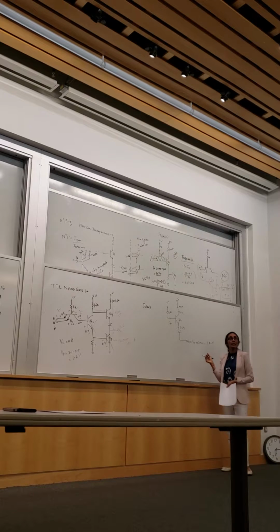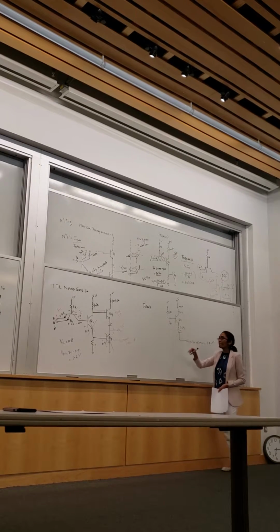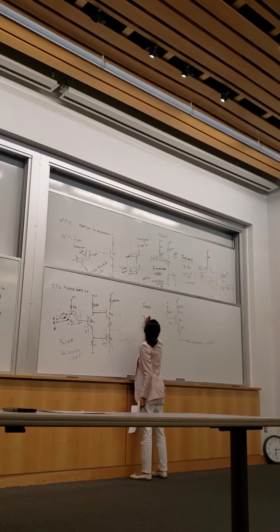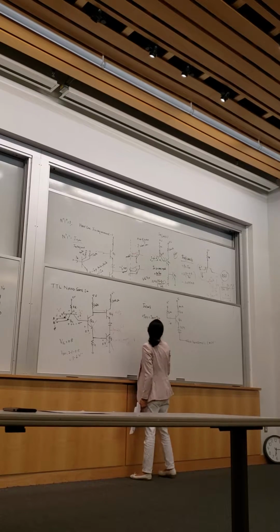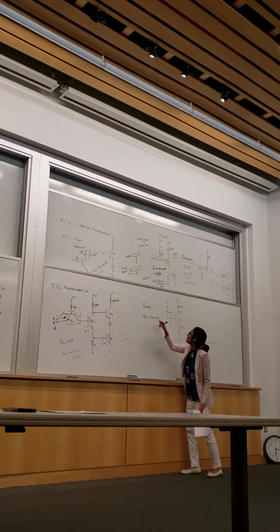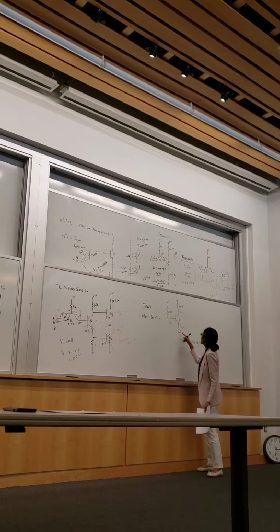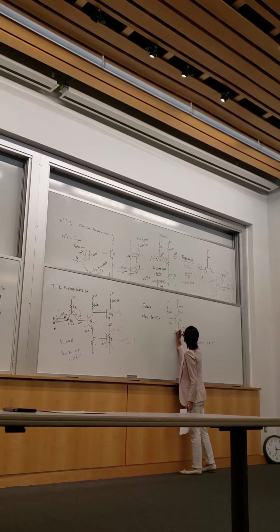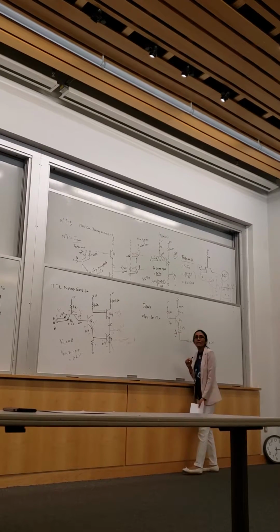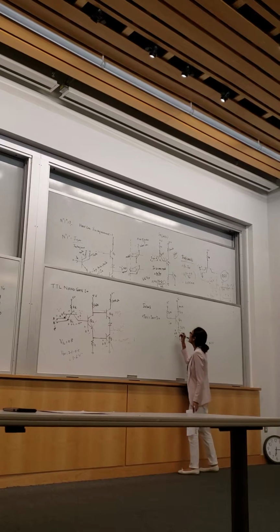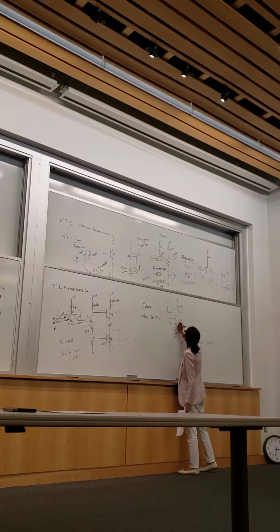So what is I not available here? IE4, right? So I not available is simply IE4, and that is equal to IB4 plus IC4. So our job is to find IB4 and IC4. What's the drop across this diode? This is on, that's 0.7. What's the drop across the base emitter junction of Q4? 0.7 volts. And can we find the voltage here at this node?